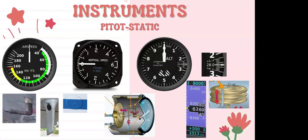In this situation, again, what we're measuring is really a pressure differential. Both of these instruments are wanting to find an equilibrium, right? The diaphragm wants to be at rest. It doesn't want to expand or contract, but it's trying to equalize the air between the case and the diaphragm, molecule-wise, pressure-wise, by expanding and contracting, which is going to give us those movements.